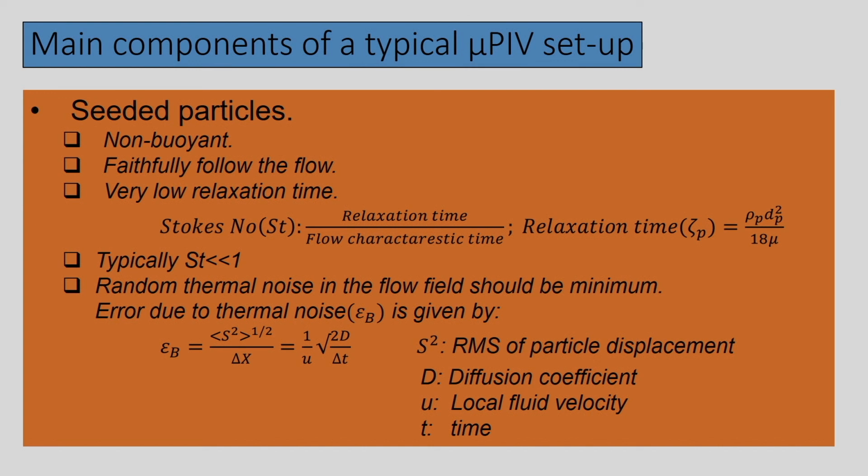I have discussed in the context of the PIV discussion that the seeded particles will have a few important features. Again I am discussing a few of them: that it is neutrally buoyant. That means the seeded particle will largely follow the bulk flow, and the density of the particles will be almost equal to the density of the fluid.